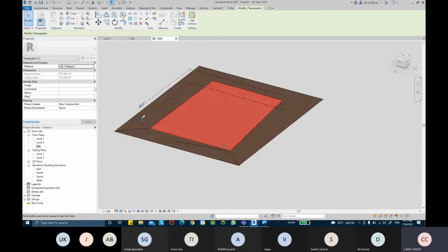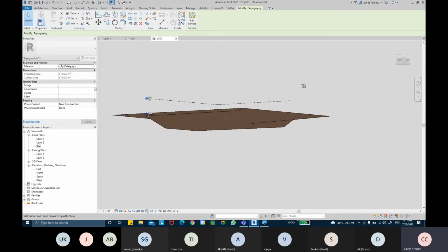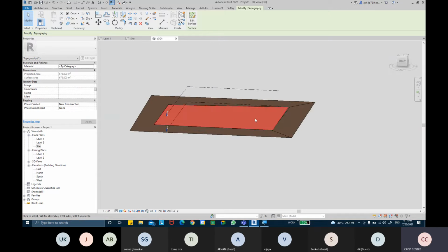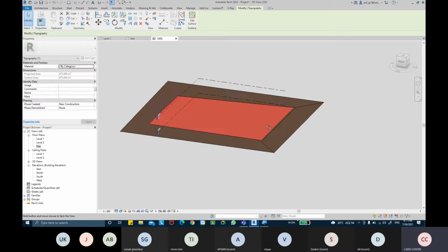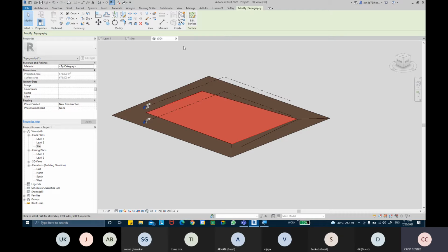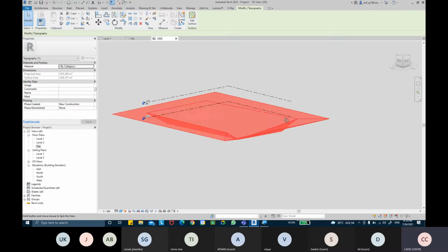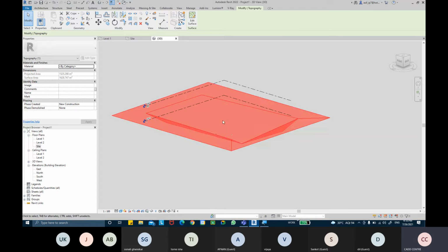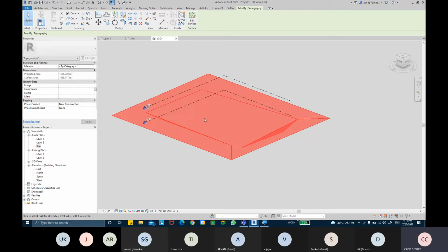That becomes as a leveled. Okay, so it's deep, but we have added another surface on the top of it so that it becomes leveled basically there. Okay, so for leveling purpose basically there we use graded regions. What happens if I pick the first option in graded regions? So if I delete this, so now again you can see there's no top surface basically there, so it's not filling that gap hole that is there basically there.